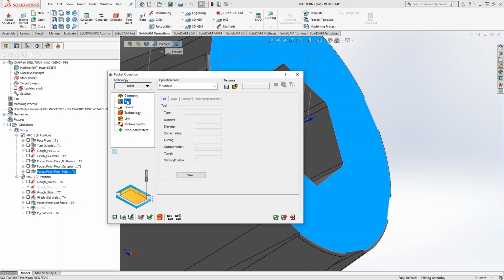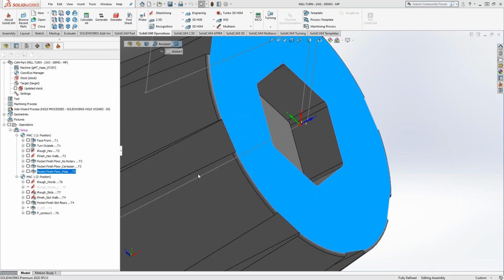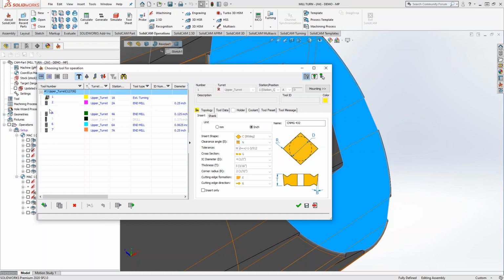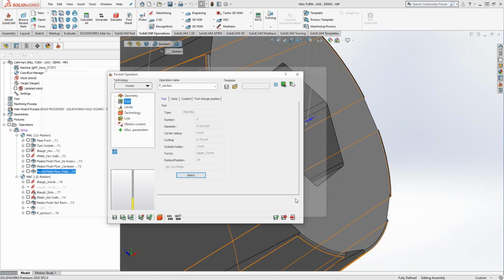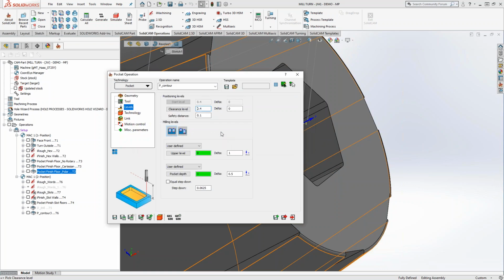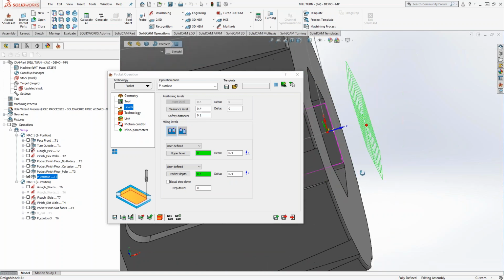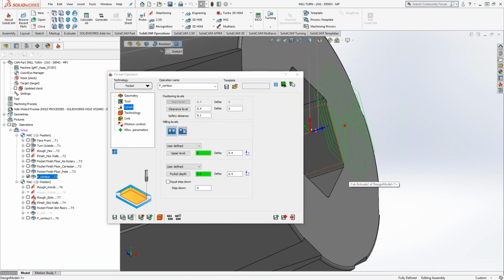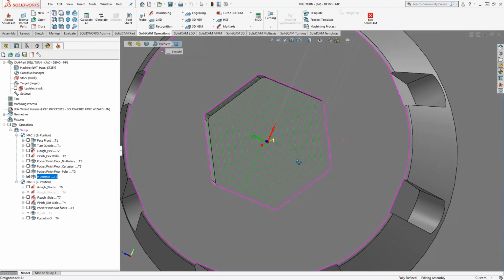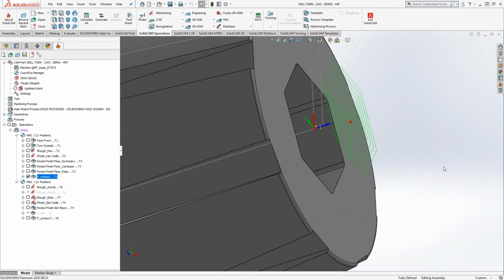And I got to get my tool, so let me choose my tool. So I'll choose tool 3 so we can get a very similar looking pocket to what we had before. Yeah, okay, so that's why. Let's not make this so high. Let's make this 0.4. And we'll make this 0.4 as well. So you see, even though our chain went up and down in z, it's projected to the same z plane. Perfect. Awesome, okay. And that actually looks pretty cool. I like that. Little spiderweb looking thing.